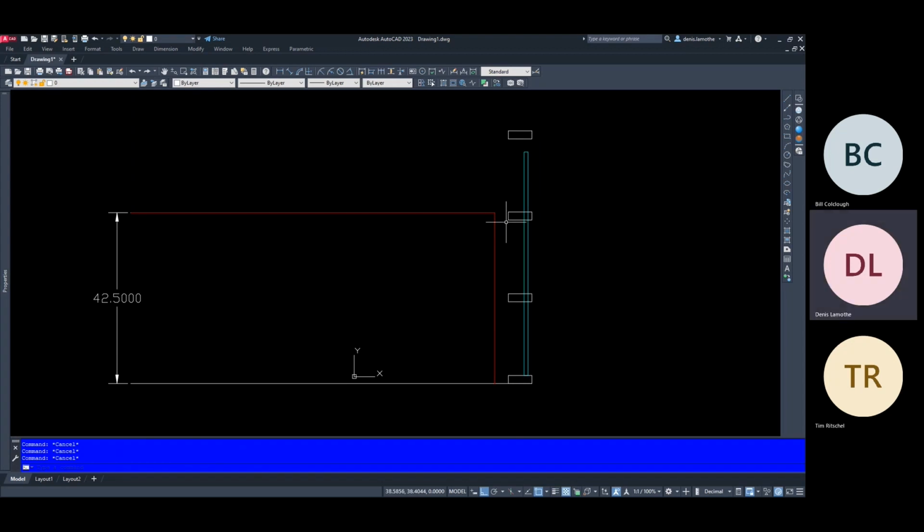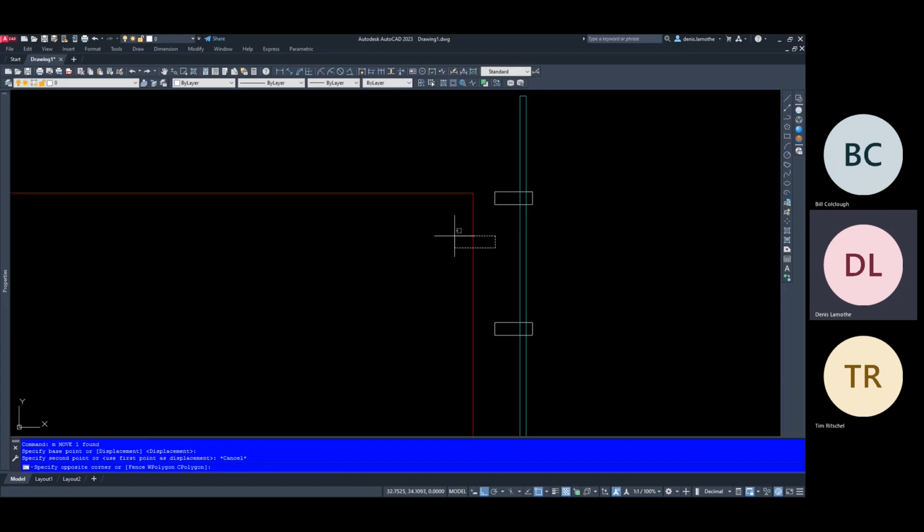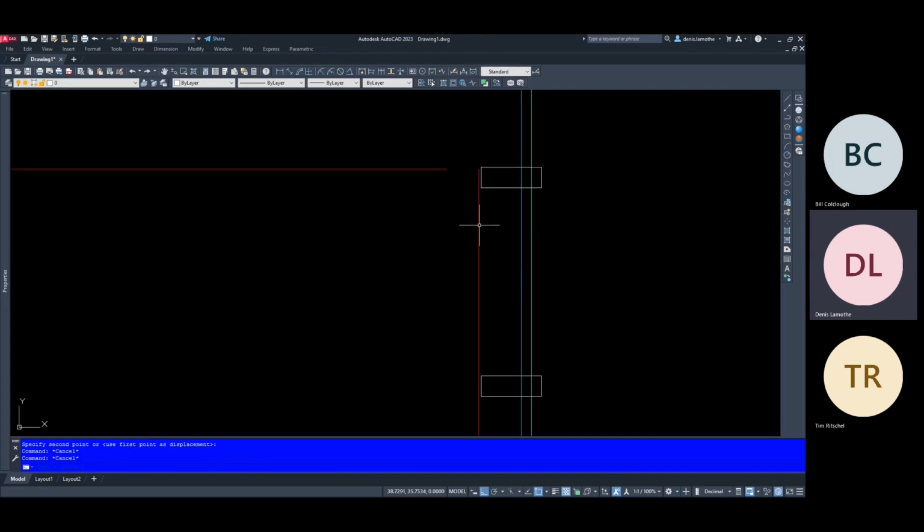We want to make sure that, obviously, this edge can't go past and into these curtain wall mullions because it's going to interfere with the mullions. Having said that, even if we snug it up tight to the mullion, or as tight as we can, we may end up with more than 4 inches to the glass panel, like in between here. These areas might have openings bigger than 4 inches.